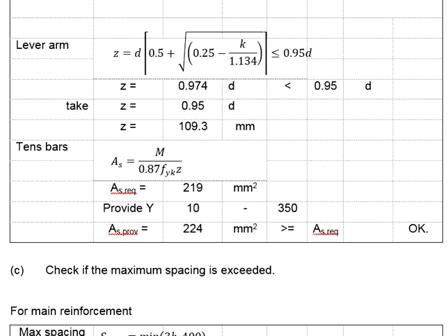Now if the reinforcement is spaced at 1 meter, there will only be one reinforcement within that 1 meter width. Then the reinforcement area would be 1 times whatever area you have calculated based on pi r square. Now if you have 2 bars within that 1 meter width, that means the spacing of the reinforcement would be 500 each. When the spacing is 500, you will have 2 reinforcements within that 1 meter width. Then now your pi r square will be multiplied by 2.